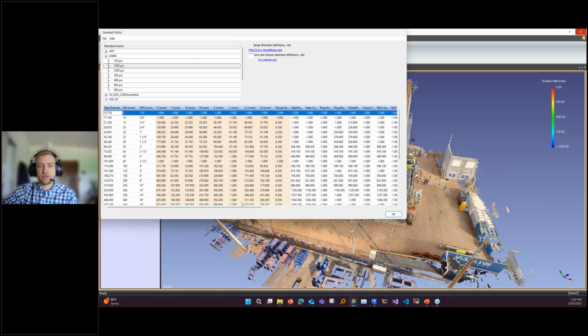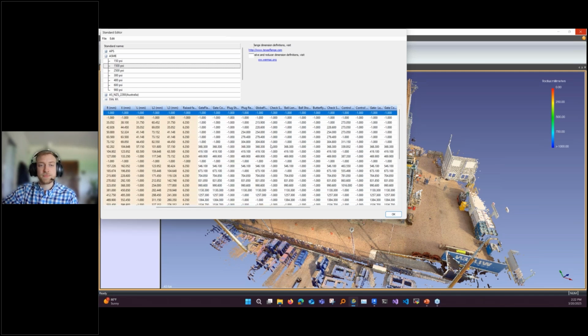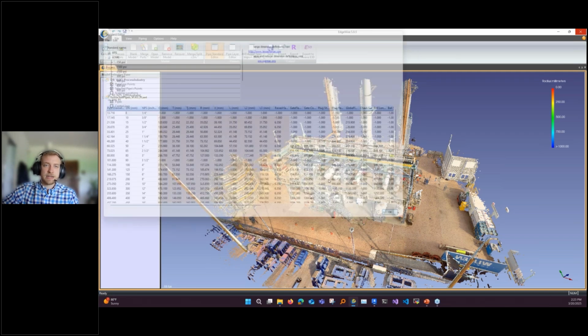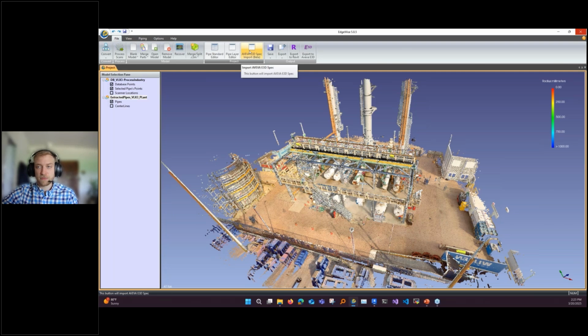And then additionally, it's very basic coverage for types of valves, and all we're doing is tracking the length of the valve. That's it. There's a bunch of mapping options, but depending on the workflow, it's really easy and fast to just create all the pipes inside of EdgeWise. It can be useful to do the valves, but if you're in Revit, you can place valves very quickly, and there are some other advantages to that workflow as well. So those are some options. And the last thing is the import function for Aveva. You go to Paragon, you can export your steel catalogs, and we generate an EdgeWise steel spec for that.